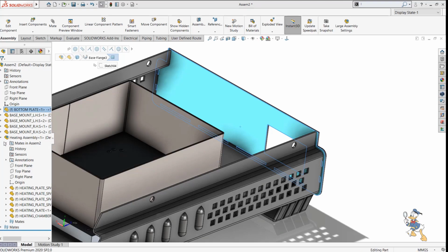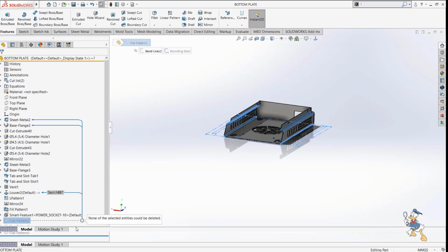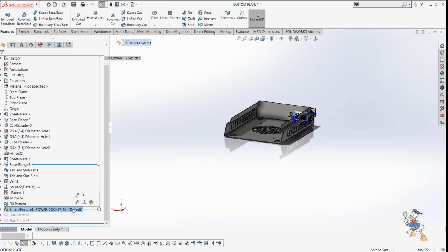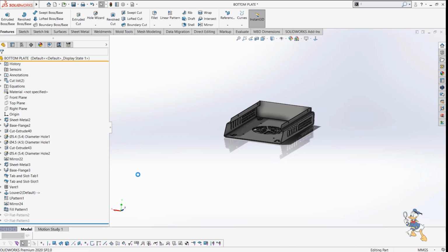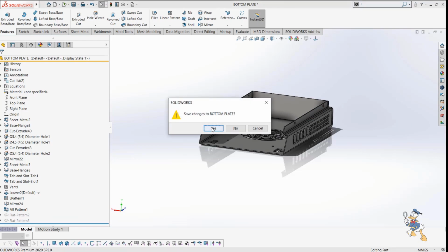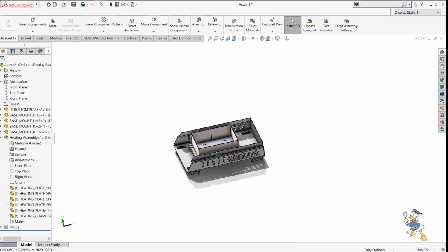So this is some sort of possibility which we can do in SolidWorks. If we want to replace it only, we can replace it very easily. So this is the feature which is available in SolidWorks, which reduces our time consumption very easily. So here I just need to make it possible. So I just need to delete this feature, Control S, and then Control W. Yeah, save changes, and the things are going happily.